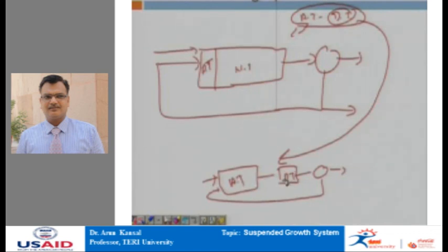So, here, since in the aeration tank we had already converted the initial BOD to near the disposal standard of 30, almost a negligible amount of food is available at this stage. If the food is less, obviously the organisms will not exert oxygen demand because the food is not there. To do that, we have to put part of the untreated water directly into the denitrification tank, so that a sufficient amount of organic matter is available for the organisms.